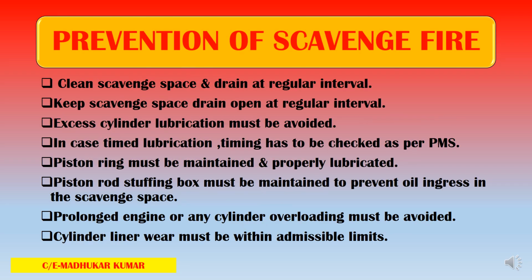How can we prevent the scavenge fire? What action, or early action, can we take to prevent the scavenge fire? Clean the scavenge space and drain it at regular intervals. Very important. The scavenge space drain tank is also there, and the sounding of that is very important.